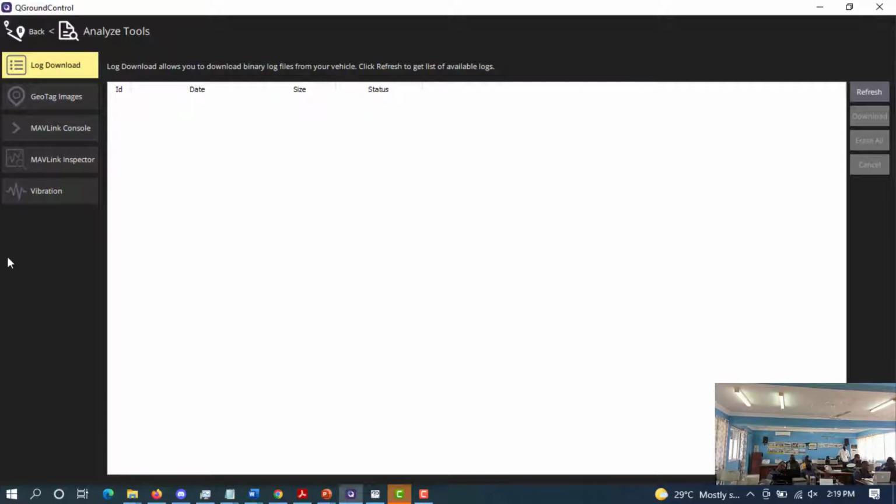Vibrations. Vibrations are basically caused by mechanical movement. You can have certain parts not tightened well, like the knobs, or the motors not mounted well, and once the aircraft is taking off and these parts are loosening up, vibrations will start setting in. When you look at the vibration graph, there is the allowable vibration and the non-allowable vibration. So the moment you start getting those issues, you need to do a physical check on the mechanical aspect of your aircraft.